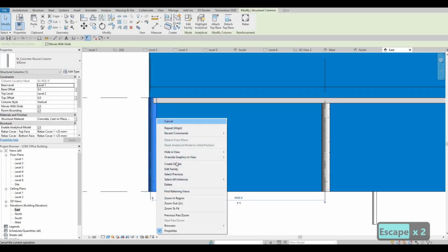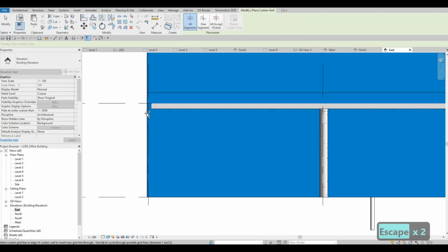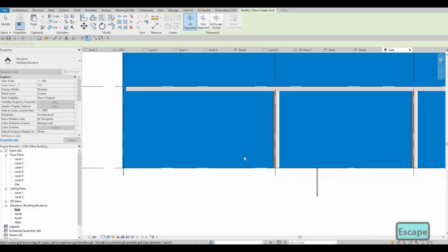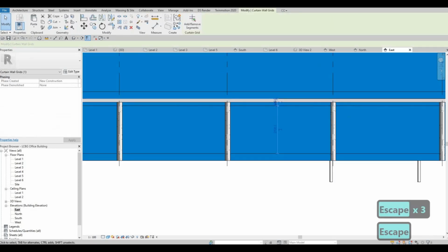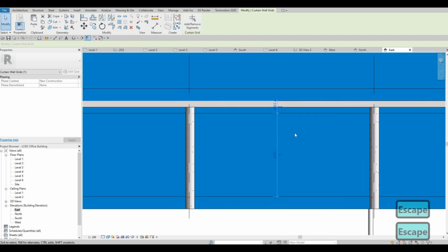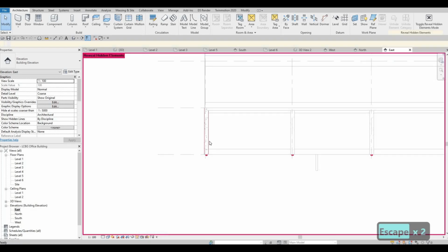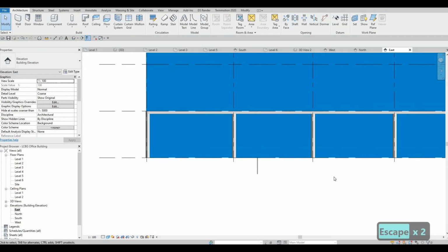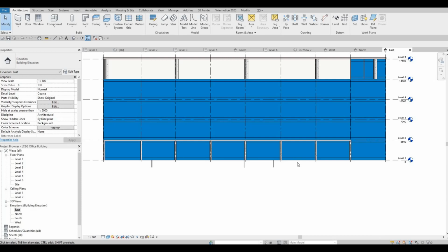What I'm gonna do is I'm gonna hide this for now. Hide element. And then just put curtain grid 400. And then here 400 as well. And let's double check that. 400. This one is not okay. This is 400 as well. So, and then now show this, reveal hidden, click it, and hide element, and then click on this. So just an easy way of undoing those.